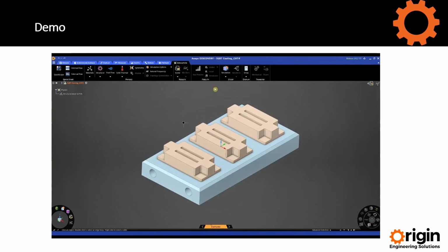For our third example, we're going to be looking at a thermal simulation. For this example, we're actually going to be looking at what we call CHT, or fluid solid thermal. And again, this is another simulation that you can do in Ansys Discovery, and you can do this in the Explore mode. So again, using that graphics processor to get speedy results and rapidly explore designs.